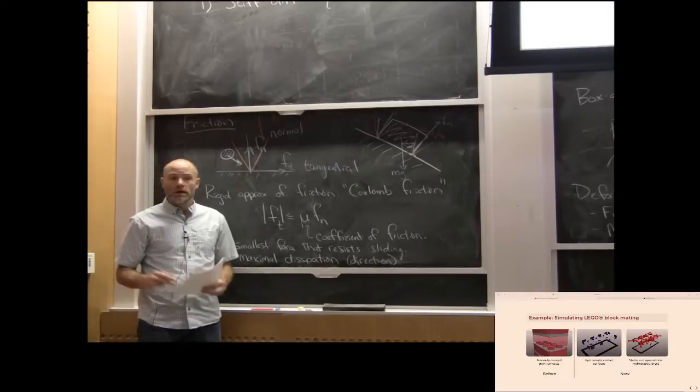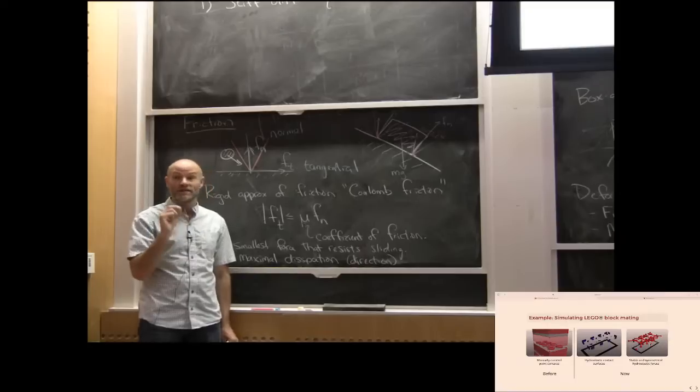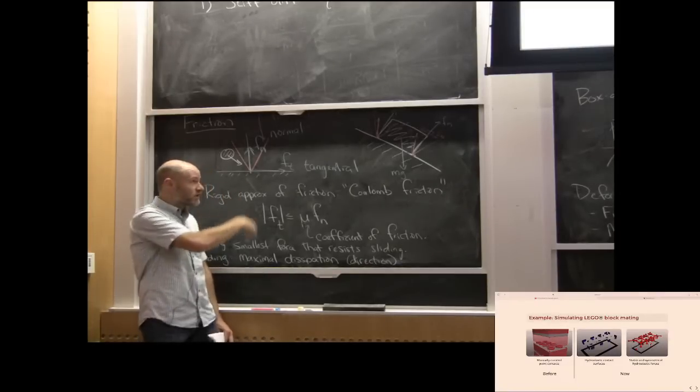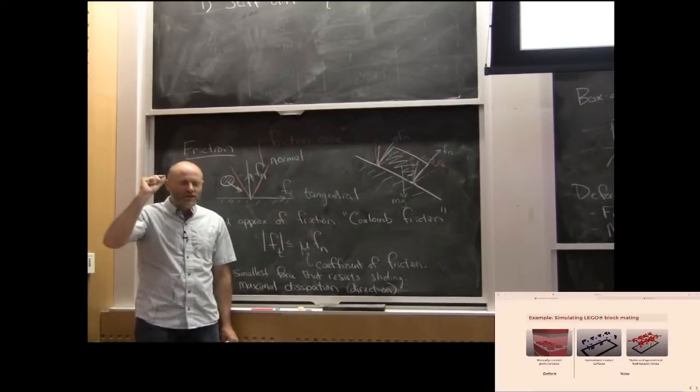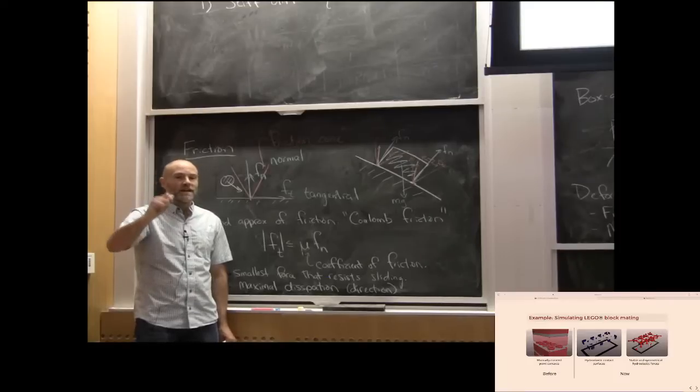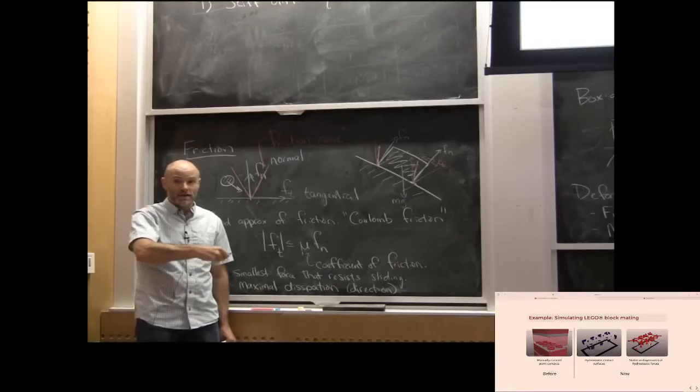Okay, so I hope your wizardry level as a user of contact simulation went up a little bit. You saw a little of what's going on behind the scenes. But if you take away one thing: if you see your feet shaking or objects shaking, the first thing you do is turn down the time step and make sure that phenomenon goes away. You should always be able to take that phenomenon away by making the time step small enough. It just might be painfully slow to simulate.